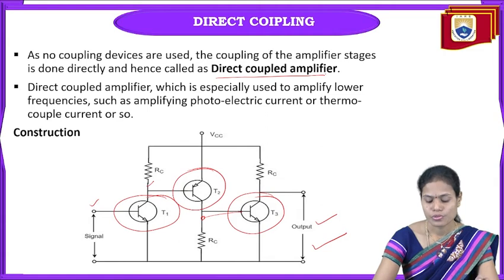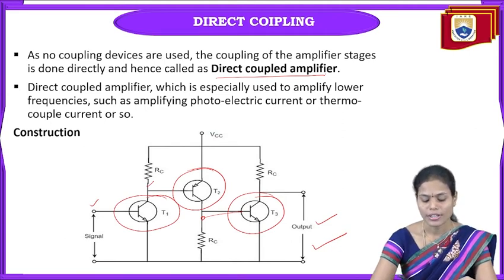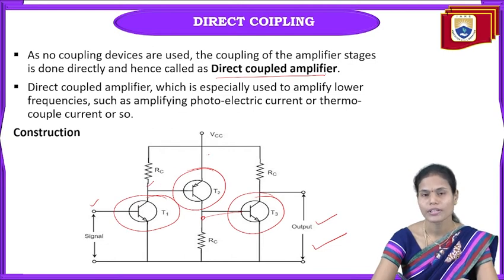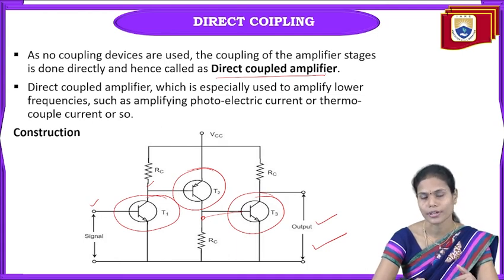Okay, so here why are we using the NPN transistor in the first stage and the PNP transistor in the next stage? Any variations in the NPN transistor are nullified by the variations in the PNP transistor. Why? Because in the case of NPN and PNP transistors, all the current levels as well as voltage levels are in opposite polarity.